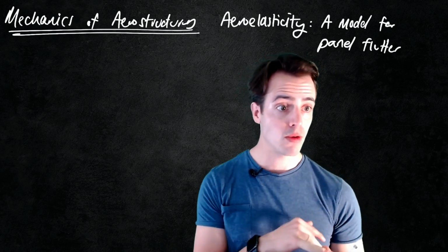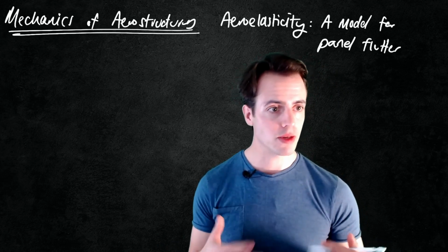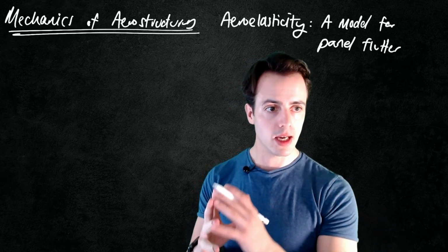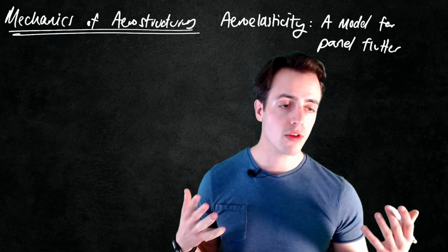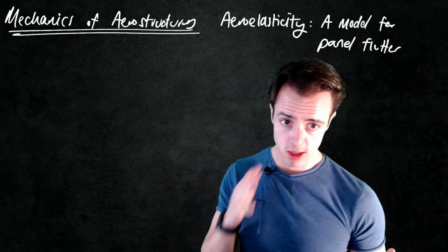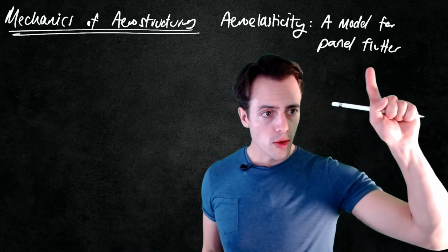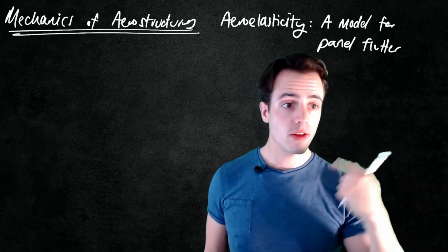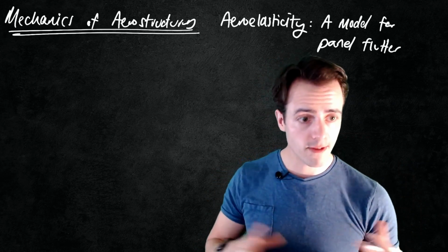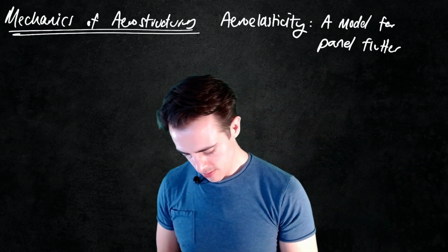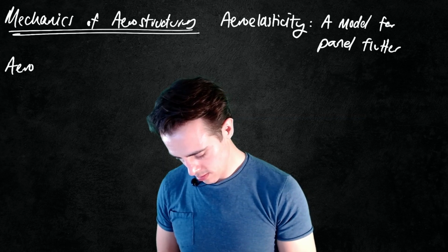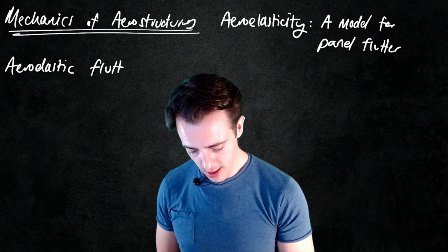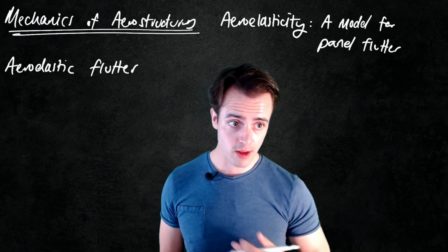So we use sort of a finite element model to build this model, and we use virtual work methods to build up the non-conservative aerodynamic forces. So it's just to show you that we do use these methods to build up real models. So flutter, we sort of loosely spoke about in the introduction to this course, and I'm now going to just talk a little bit about flutter and what it actually is. So aeroelastic flutter, as distinct from atrial flutter, which is something that occurs here.